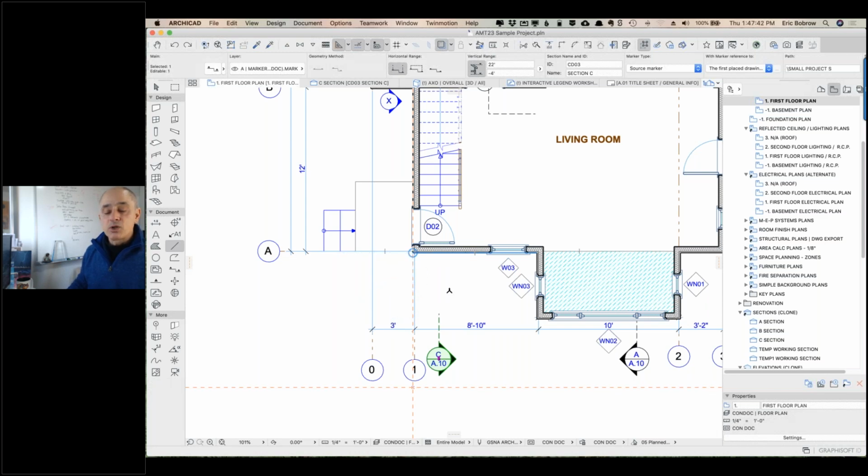Now if you want to do it more quickly, as Tom pointed out, if I'm just going to bring this over and hit Q immediately, you can see that it instantly shows that snap point, as well as in this case, the distance between the two most recent snap points and the arc, which would allow me to potentially draw something an equivalent distance away. So Q will turn those guides on and off, or instantly turn them on.